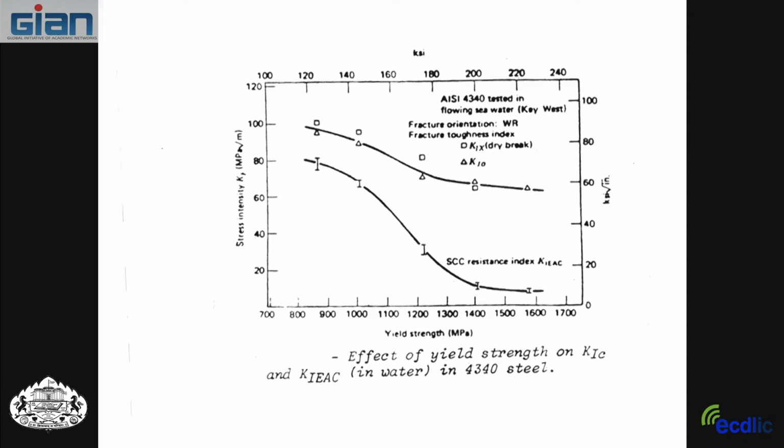This would be closer to a K1C. They didn't call it K1C because I don't know if they did actual K1C tests or whether they got a KQ or what happened. But here, this is important in some applications causing failure: if you get in the high strength area, you are really in a dangerous area.